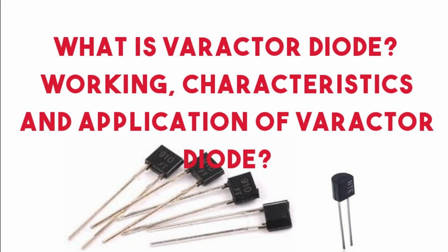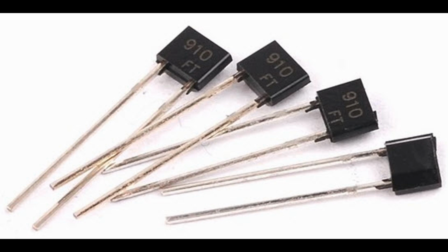3. Resonance control. Many VCFs also provide resonance control, which emphasizes frequencies near the cutoff point. Resonance can be adjusted using a voltage input to create a characteristic peak in the filter's frequency response. 4. Bandwidth control. For certain filter types, such as band-pass and notch filters, the bandwidth can be controlled by voltage.